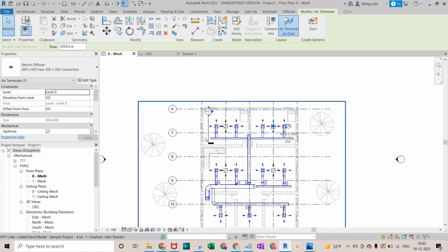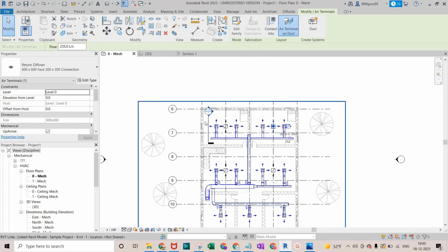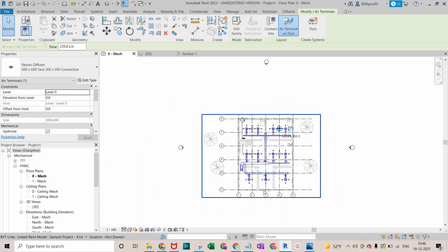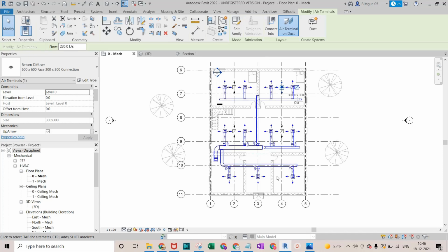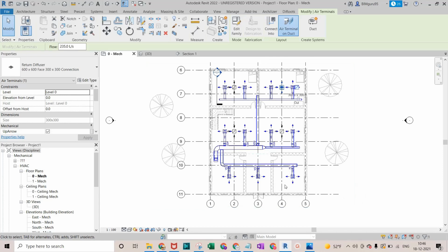And exhaust as well. For the exhaust, we sometimes have a ducting system, and sometimes we just use the exhaust grill, something like that. The same thing will be drawn for the exhaust air also, but it will be exposed outside of the building by a louvre or something like that. Sometimes it doesn't connect with the AHU, and sometimes it connects. It depends on whether you have a heat recovery unit, and there are many more things as well.